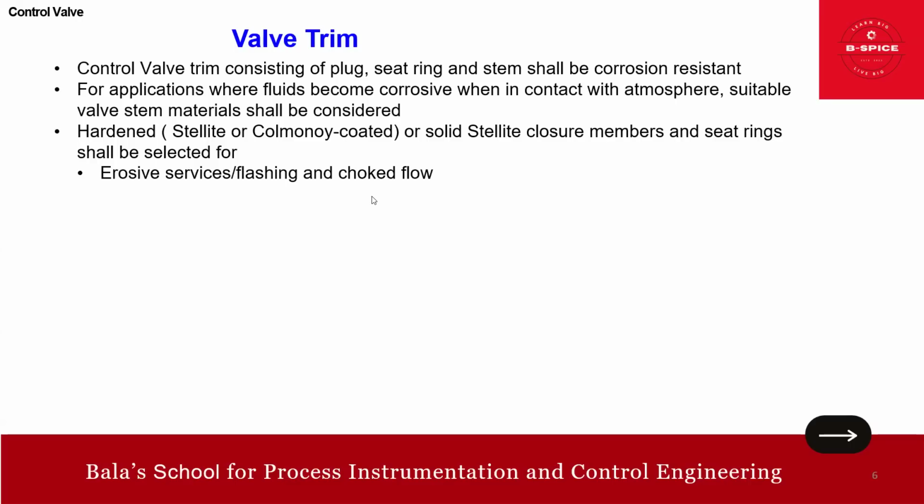Okay. So again, do you have any question on this? What is flashing? What is choked flow? I have already updated this in detail. If you want, I can go through it. Again, just as a recap, flashing is a condition, friends, that occurs with liquid flow. Always remember, when the pressure falls below the vapor pressure. All this is a common interview question.